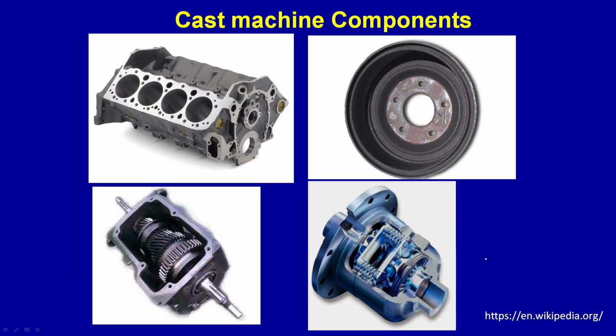Well, not only that, many machines, actually machining things, are made by castings. Let us talk about a car engine. This is a 4-cylinder car engine. You can see there are 4 cylinders. This is a single cast product. It can be made of cast iron or of aluminum silicon alloy. Nowadays, many car engines are made of aluminum silicon alloys.